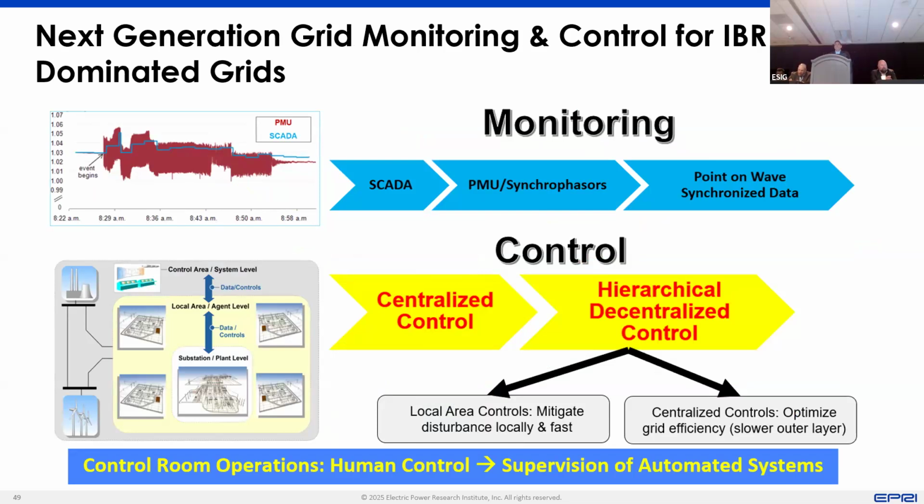One thing which I did not mention is that some of these high frequency oscillations, or subsynchronous oscillations, PMUs cannot capture. So there is a lot of research now in industry on how synchronized waveform measurements can be used to detect those kinds of oscillations. So a lot of work is going on in that area as well, which I don't think I have time today to present.